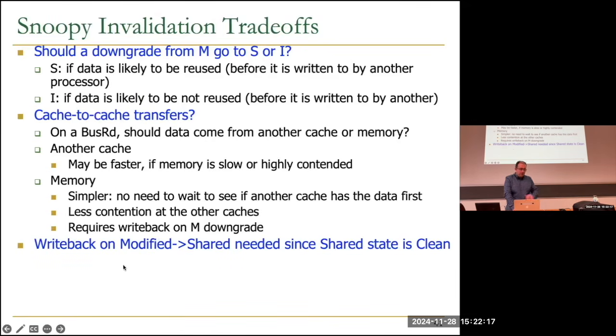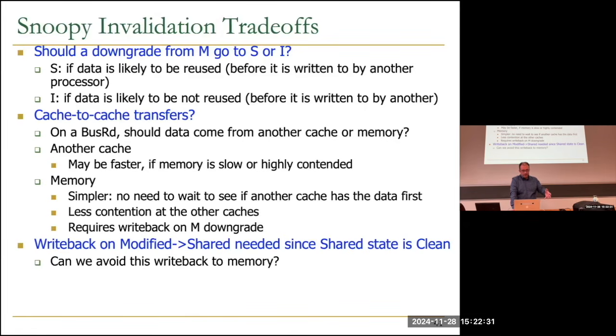And that brings us actually to another model, which is Owned. Write back on modified to shared is needed since shared state is clean. So that's the definition of shared state, which is clean. So when you want to go from modified to shared, you need to write back.